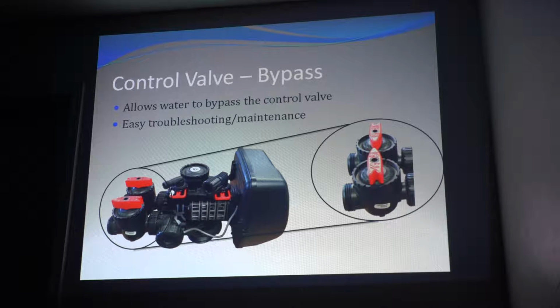The bypass assembly allows a water softener to be bypassed so you can service the control. In Wisconsin, it's state code that you have a means of shutting off the water softener without interfering with the water supply to the home. If you don't put a pre-assembled or pre-manufactured bypass assembly on, you have to plumb in a 3-valve bypass, which yesterday you got the experience doing, Todd.